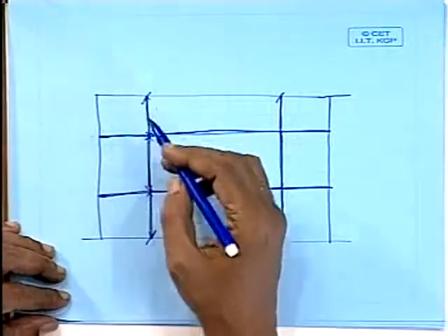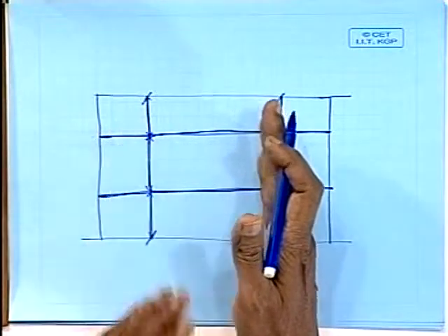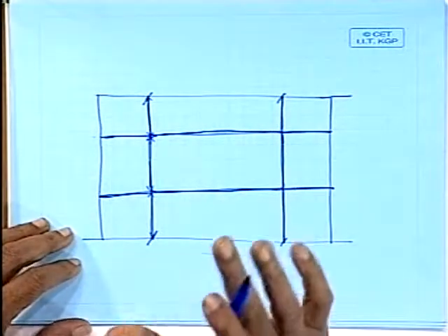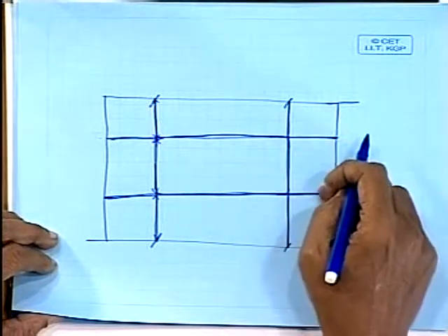One more thing you may note is that the hatch end beams are transverse members. They will not contribute to longitudinal strength. So if you design the girders taking this span, then the girder is of bigger dimension contributing to longitudinal strength, where the girder is right at the top. Therefore, its contribution is much more, isn't it? You have done I by Y calculation, isn't it? You calculate I about the neutral axis. So if it is farther away, its contribution is more. Since we are talking of the deck level, if I design my girder as a primary member, then its contribution to moment of inertia is much more.